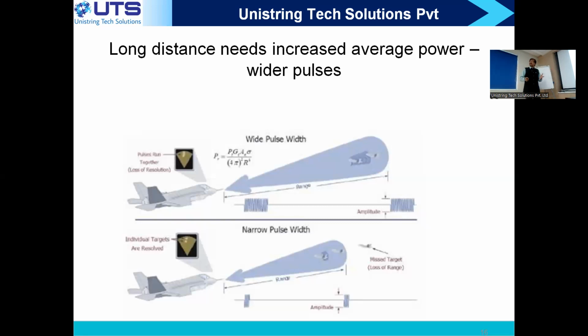That's a beauty, actually. But it has a problem: range-wise, your range measurements get compromised. Just now we discussed, your pulse is so long that the first target and second target echoes are merging on each other and coming to me. Here, a new category of the subject comes into the picture, called pulse compression. So it's a subject in itself.